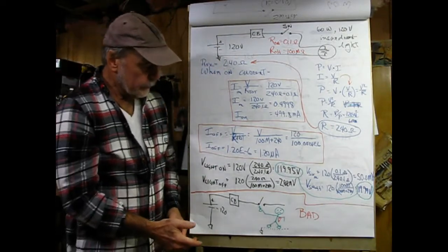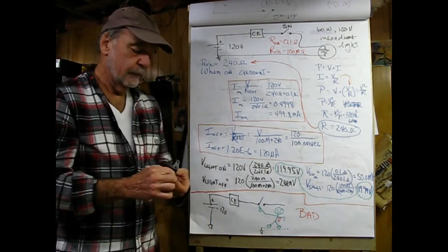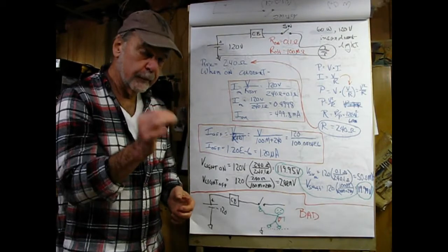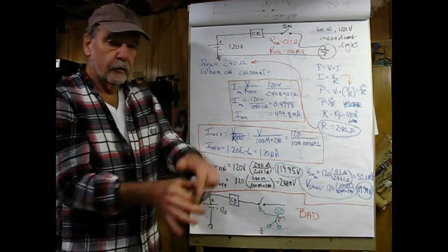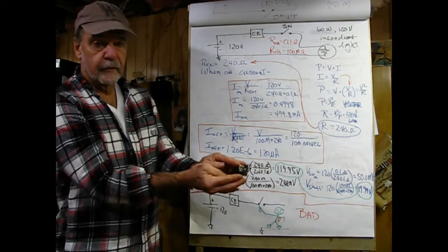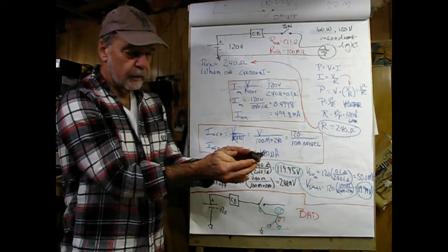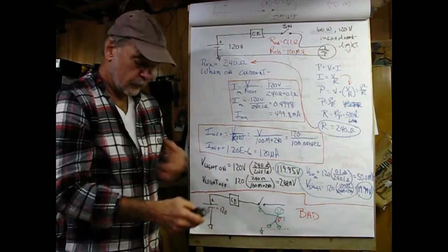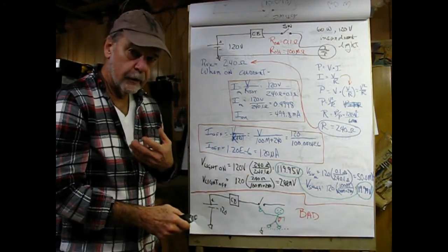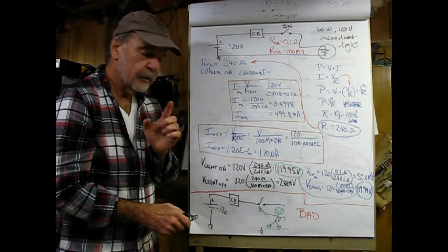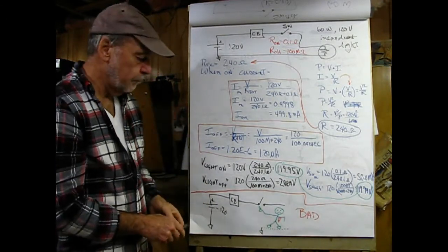So across this here, as I've shown, I've got my fingers here, and that's going to hurt, but it's not going to kill me. The reason is that the current flow is simply going to be through my hand like this. Now, if I were to touch it like this, say when I was working on it with a screwdriver, different story. Current now flows through my body, crosses the chest cavity with your heart. Bad things can happen, especially if it's AC, because AC is more dangerous than DC.